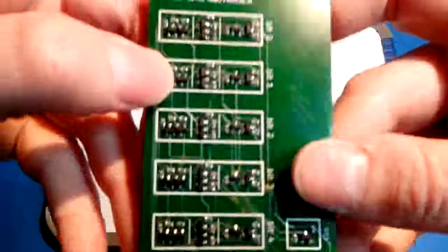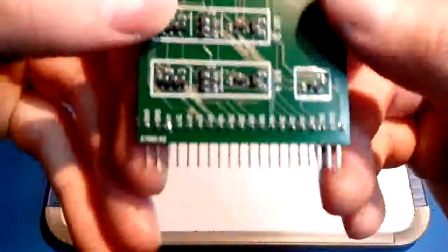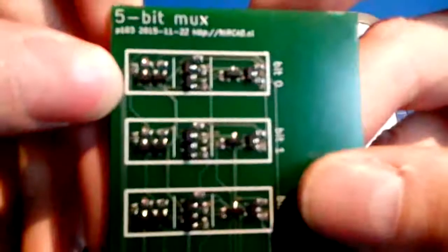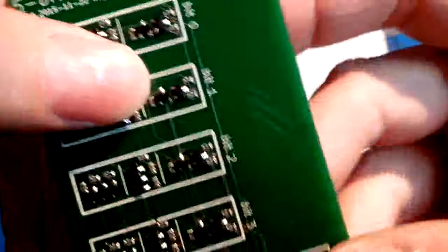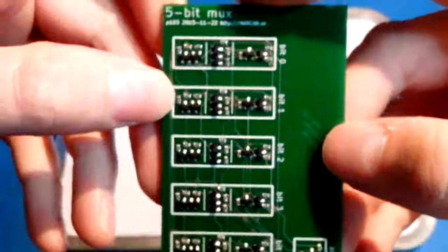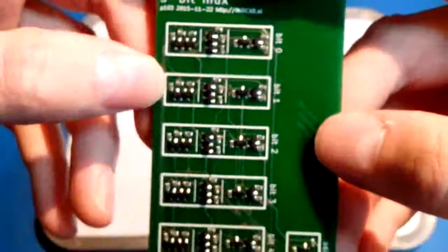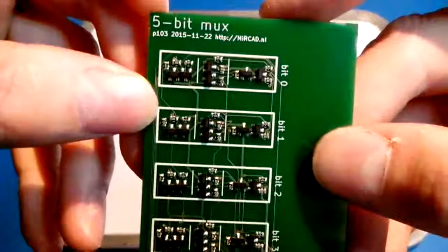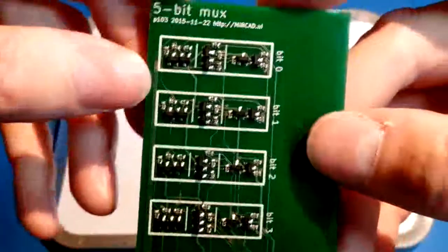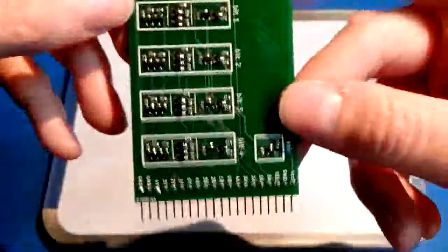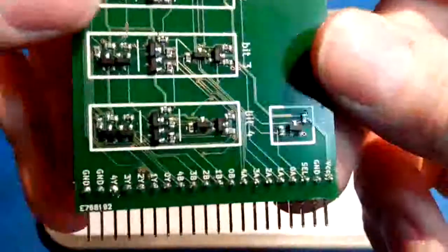This is a 5-bit multiplexer, as the text says. So this was a bit of a design error. It could be a 4-bit multiplexer, because in total we need 16 bits, and you would need 4 of these boards and then throw away 4 bits, or you can simply make modules that implement a 4-bit multiplexer and put 4 of these in the CPU and also end up with 16 bits and not throw away any bits. So this will probably change on this board in a next version.